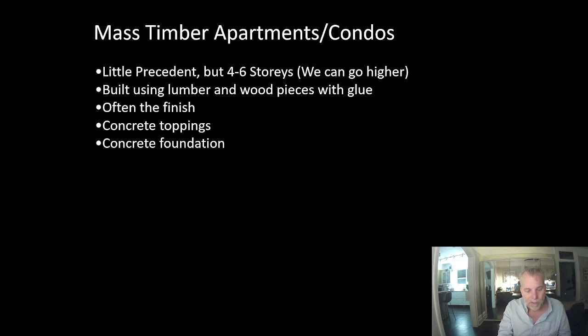Wood can be the finish, which is a tremendous benefit. It is acoustically reflective, like concrete is. So if acoustics are a concern, you wind up covering portions of it. Wood is lightweight, which means that sound transfer is a problem where it isn't for concrete, and often we'll end up putting concrete toppings on for acoustic reasons. We typically use concrete foundations, mass timber.